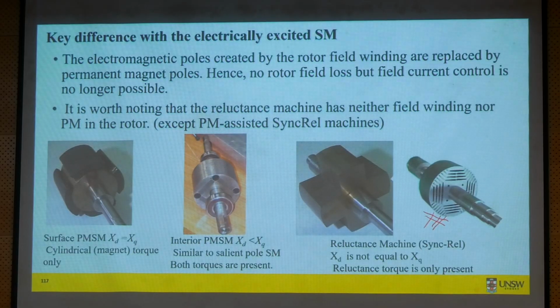If we use this rotor, which is quite common in switch reluctance machine, okay? Switch reluctance machines use a reluctance rotor like this. If we simply use this reluctance rotor, the problem is you could have very large torque ripple. Switch reluctance machine is quite well known for its noise, vibration, and torque ripple.